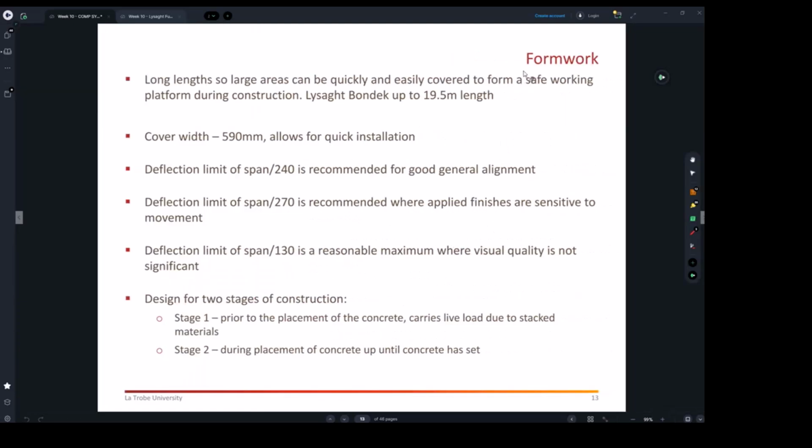Okay, so we're talking here about the formwork, and as I said to you, we've gone through all those features, but I'm going to cover them for you again. The bonding length can be as long as your transportation allows. It says here it can come up to 20 meters if you want that expensive transportation arrangement. But on average, usually a 12-meter transportation length will be more economical.